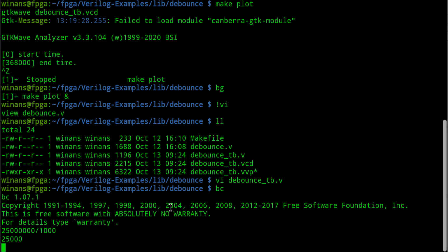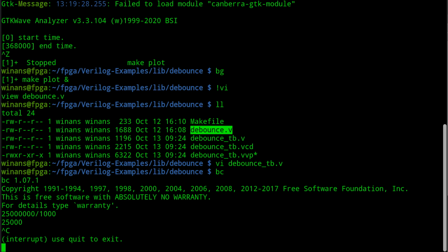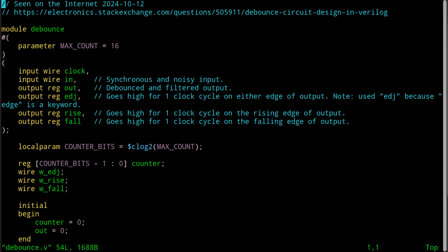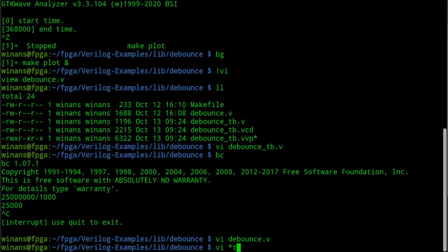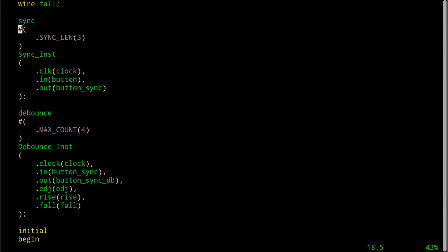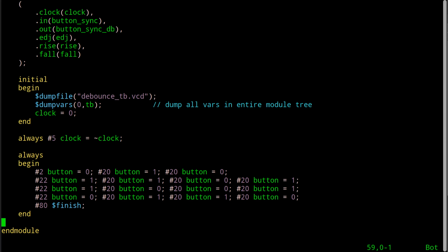You know, if you have a whole bunch of push buttons in your circuit, and each one of them has a debouncer on it, you're probably going to need a debouncer on every one, and each one of them has 15 bits of count. That's the max count. If you needed to, let's create the test bench here. If you wanted it to go out that high, you would need to count this to 25,000, which is insanely big, right? So in this scenario, you'd have to multiply all these by some giant number, is my point.